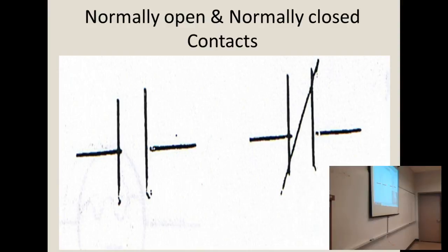But anyway, I don't have that here. That's going to pull the armature down, the plug. On the back of this, if we took this apart, you'd see there's a steel plate. And when this becomes magnetized, it pulls it to it. That overcomes the spring. Here I have it inside of a relay. A relay, same thing. I don't know if y'all can see this, but there's a coil here. When it does, it pulls the spring here, and it makes out here this close, and lets power flow through, right?